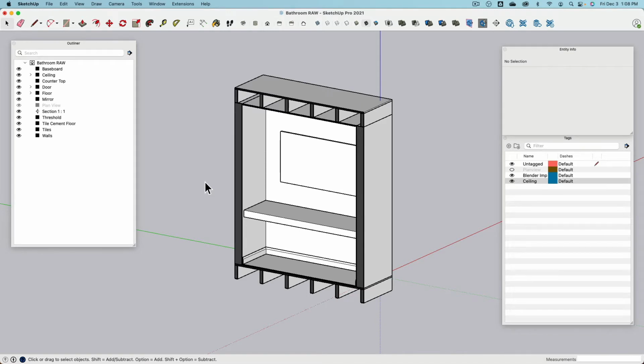To design a cabinet system in SketchUp, a particular system we would like to be replicated multiple times, and when we modify one element, we want the other elements to be adjusted too. SketchUp actually offers a really great tool set and process. And the component system, what makes it so special in SketchUp, is that I can not only take one object and turn this into a component, I can take multiple components and turn this into another component. So I can nest them. That's actually pretty unusual and works really fantastic. It's more how assemblies work in engineering programs.